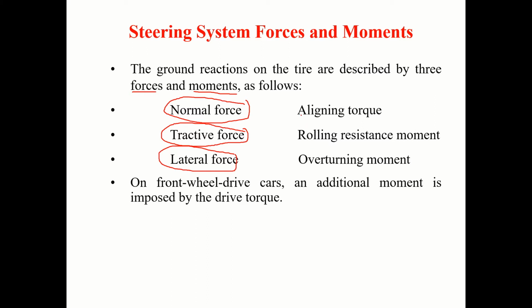The moments are aligning torque, or you can say aligning moment, rolling resistance moment, overturning moment. On front wheel drive cars, an additional moment is imposed by the drive torque.